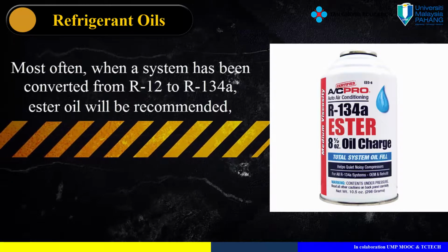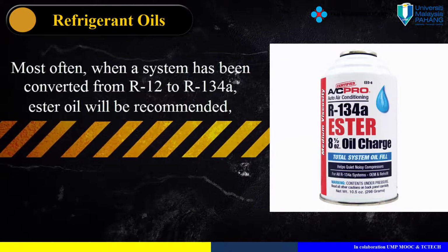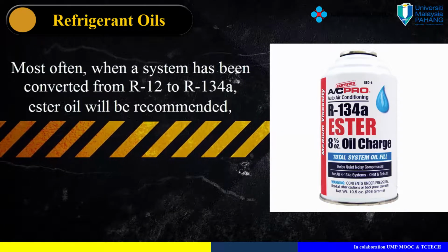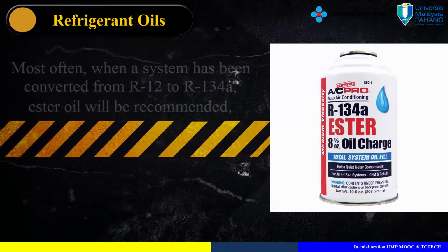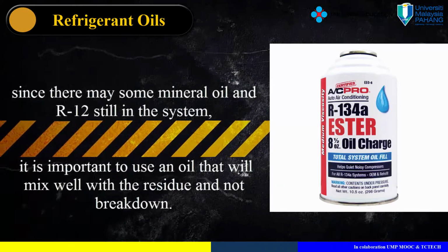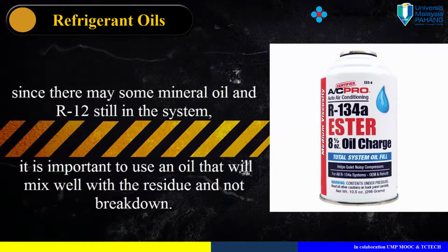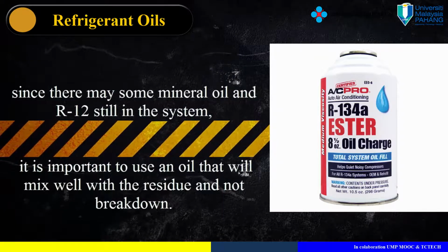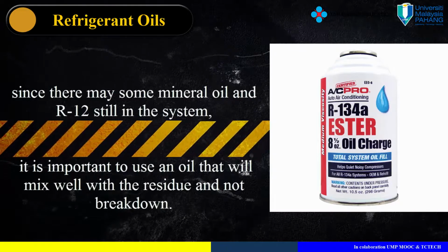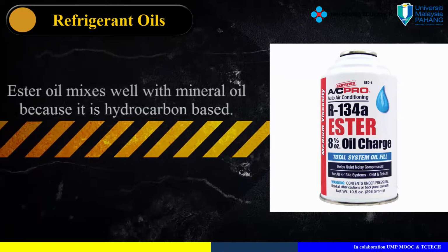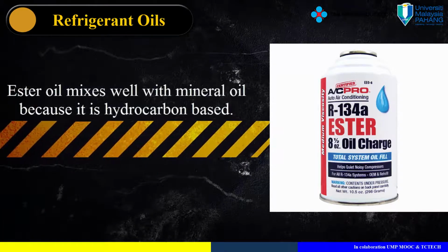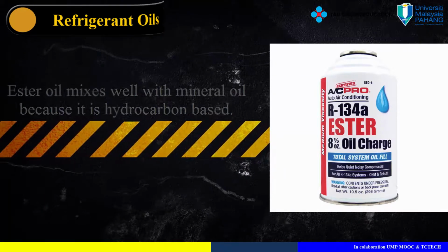Most often, when a system has been converted from R12 to R134A, ester oil will be recommended. Since there may be some mineral oil and R12 still in the system, it is important to use an oil that will mix well with the residue and not break down. Ester oil mixes well with mineral oil because it is hydrocarbon-based.